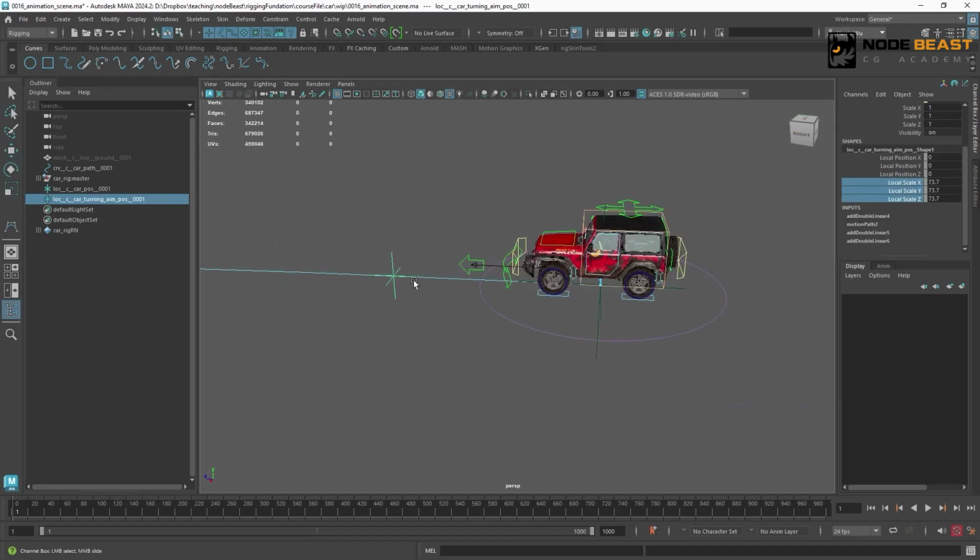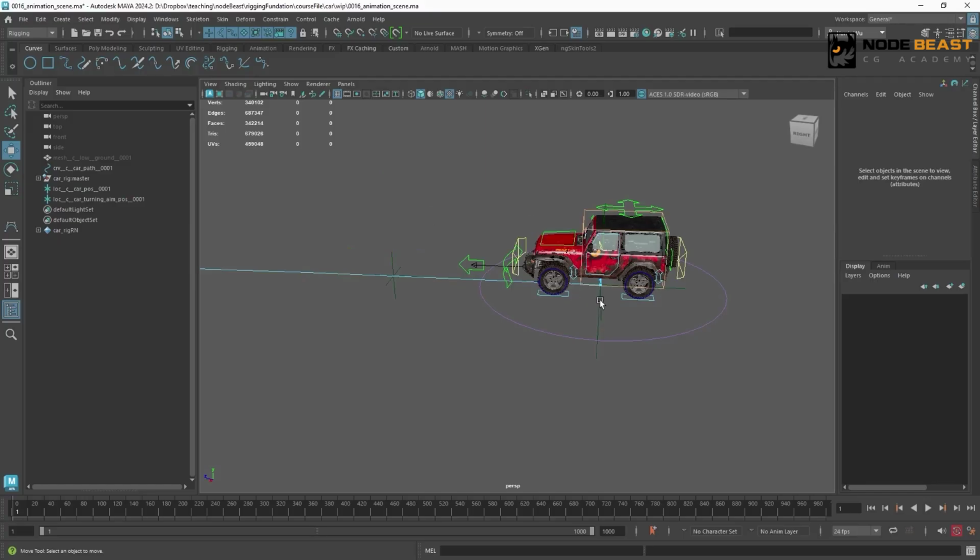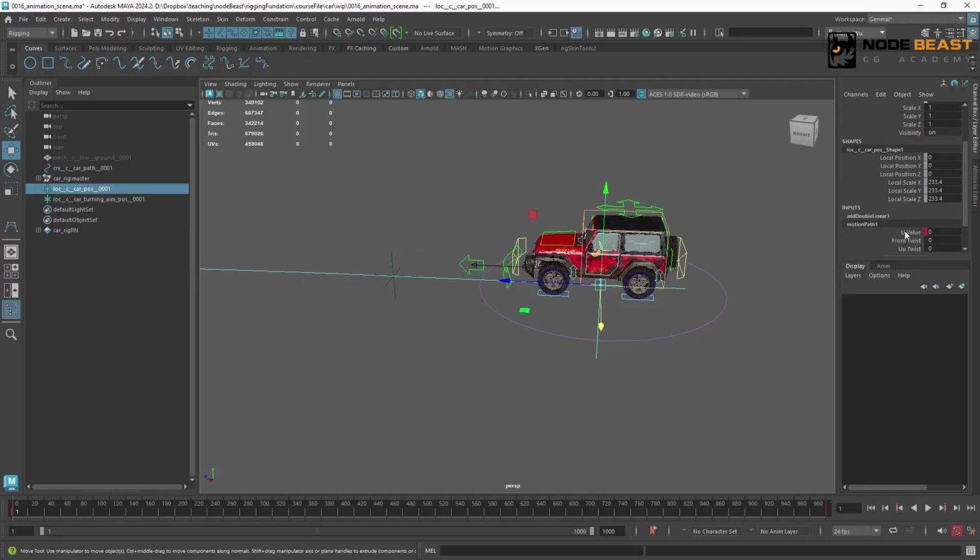But I don't want to set any animation keyframes for it anymore. Because for the animator, they might adjust the car locator's u value based on the shot's effect to decide how much the car actually moves forward or backward during a certain period. At this time, we want this front steering locator to always stay in front of the car. But if we have to set keyframes for it too, then the animator has two attributes to adjust. That would increase the workload, and it's very unnecessary. Because we know this locator just needs to stay ahead of the locator representing the car itself. So here, we can actually use the car locator's u value plus a value. This ensures it's always in front of the car.